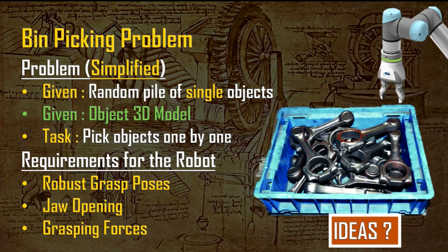Are you aware of the inverse and forward kinematics models, maybe? Yes. So once you determine the grasp poses from a deep learning system or any other way, you feed it to the end effector position, and then with inverse kinematics we get the joint positions. All the joints go to that position, it goes to the grasping position, and then you give the command of closing the jaw, picking up, and going to a home position. Was that your question?